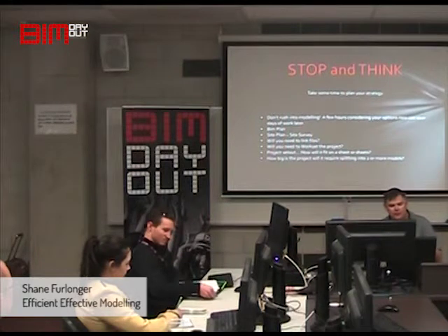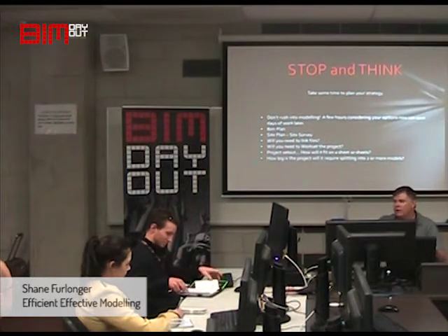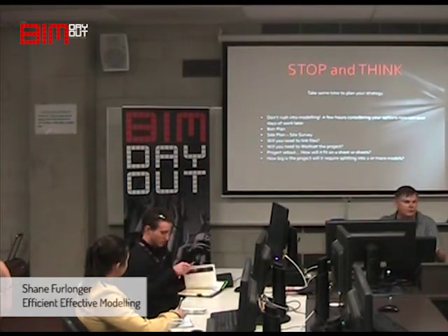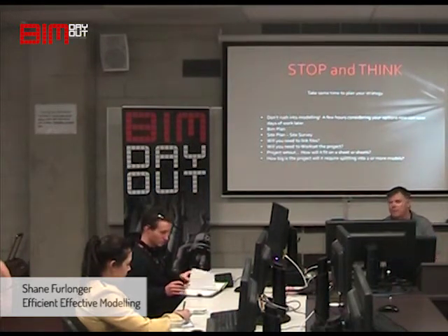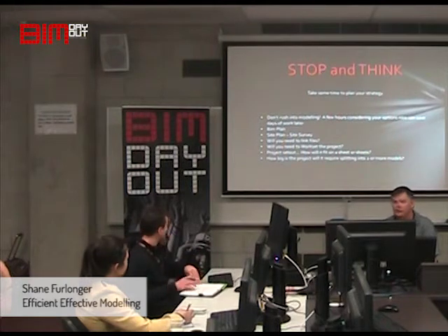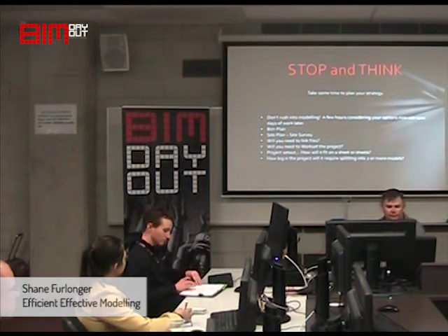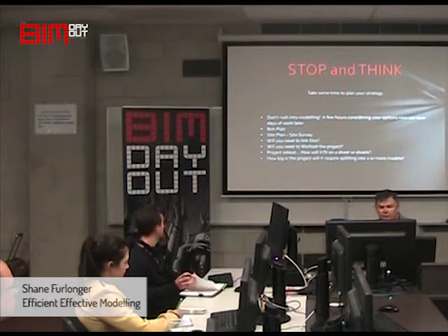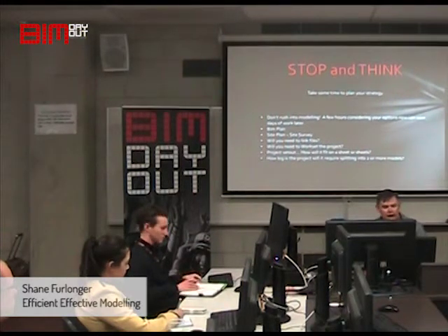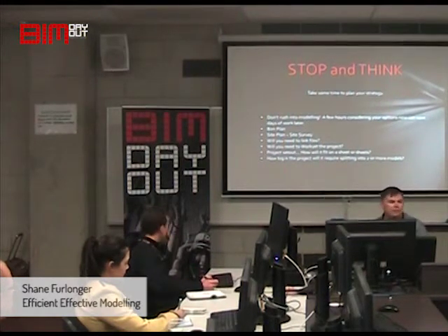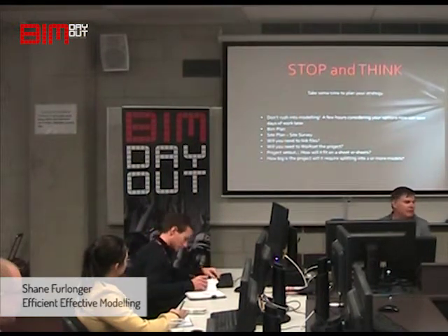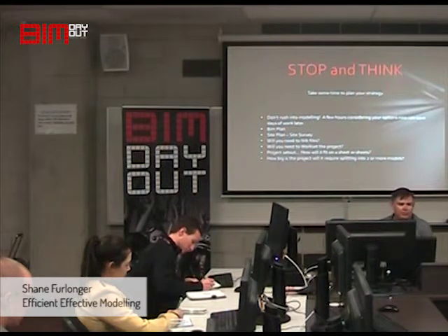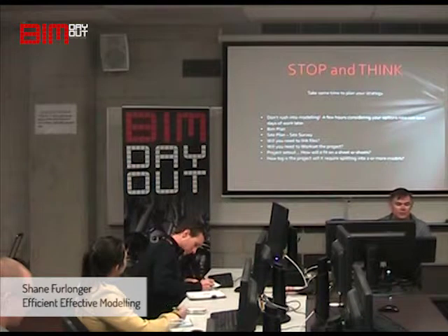Because if you rush in, you've got your model around the wrong way compared to where you want to put your sheets, all sorts of things. It can be remedied later, but you're better off if you can get them up front and done at the start. So the first thing I would say is don't rush into your modelling. Plan it out. If you've got a BIM plan, use it. If you haven't, get one. There's some available on the net. People have written up BIM plans that you can steal or you're welcome to use.